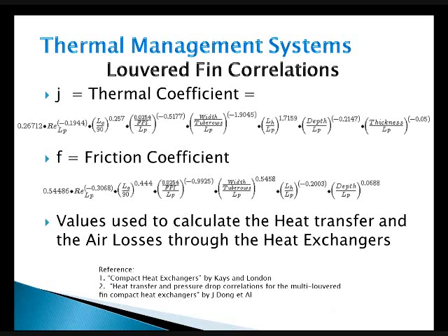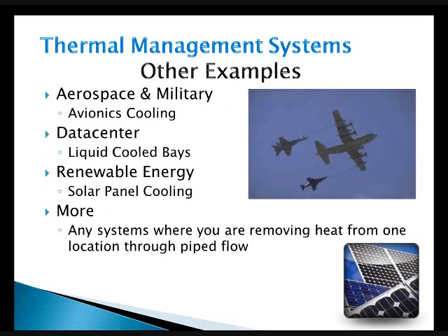What are the fin thicknesses? If it's louvered fins, what's the angle of the louver, and things like that are available. Really, for the most part, you can go out and measure with a ruler. So this should be something that anyone in the shop could go out and tell you what the values are going to be. Some other examples for thermal management systems are avionics cooling, data centers, solar panel cooling, and really anywhere else where you're trying to remove heat, as I mentioned, from one location to another.